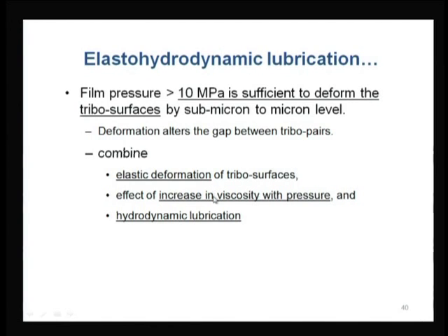That is why we differentiate between elasto-hydrodynamic lubrication as soft EHL and hard EHL. Soft EHL means elastic deformation can be considered, but not the viscosity effect or viscosity thickening effect. And the other mechanism, hard EHL, is where the viscosity as well as the deformation need to be considered. Both the surfaces are hard, and it requires substantial pressure to deform the surface. If the pressure is very high, then the viscosity effect also will be dominating. Of course, to some extent it will be decreased because of the velocity effect.